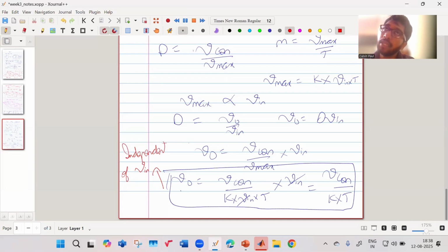They also have a method in which they divide that input voltage by the square of the RMS value of the input voltage, such that the loop gain is independent of the input voltage. It's a very standard technique which has been there for many years.